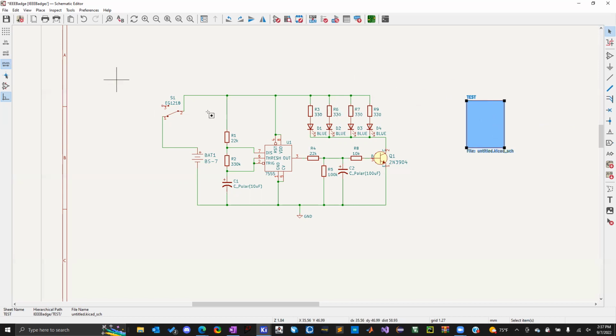This schematic has absolutely nothing to do with what the actual PCB will look like. As far as minimizing the size, there's nothing that'll automatically do it. You'll have to do it yourself physically and mess around with the traces. But once you actually place the traces, if you make the wrong connections on your PCB, you'll get a warning, and I'll show you all that. It'll also show you, based on the schematic, that pin 2 of this switch should connect to this pin of the resistor, with a general white line showing how you should connect on the PCB.